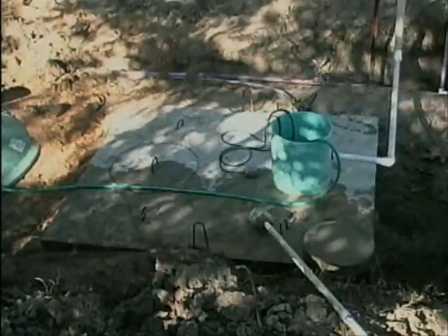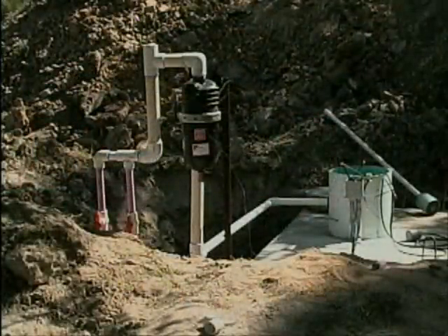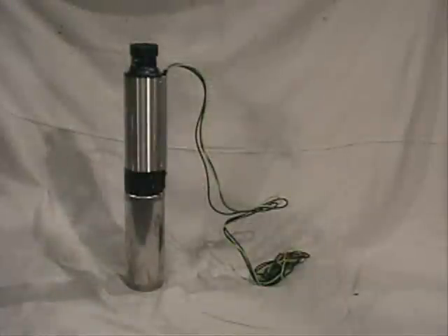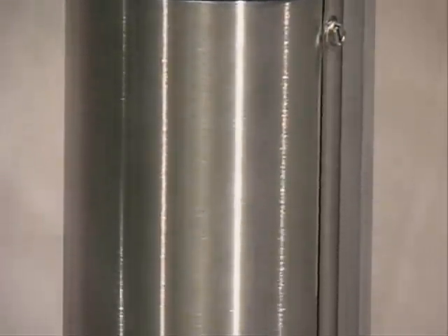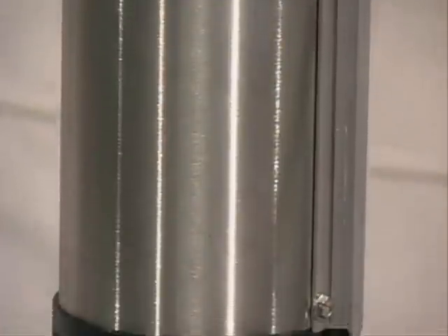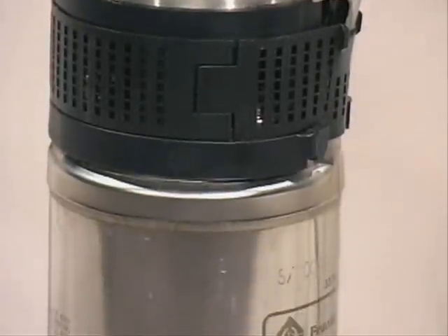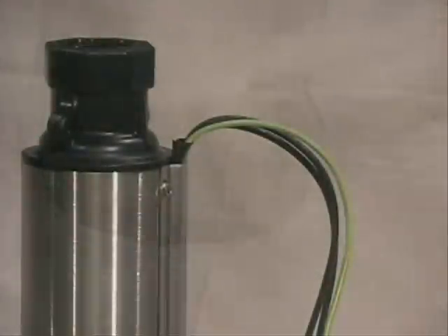The size of the pump tank is based on the expected flow variance and the emergency storage requirements for the system. The pumps used to dose residential drip fields are high-head pumps. These pumps are generally very similar to water well pumps. They provide a pump flow of approximately 12 to 20 gallons per minute.